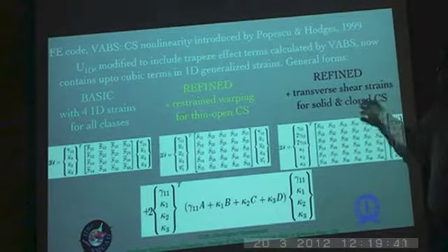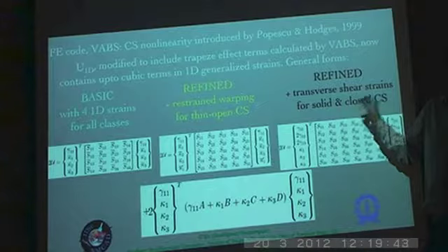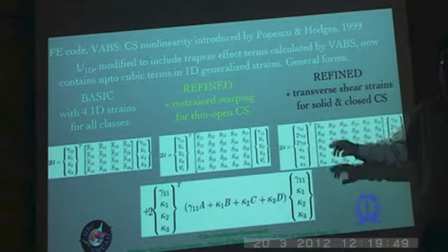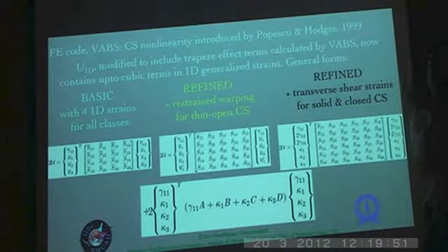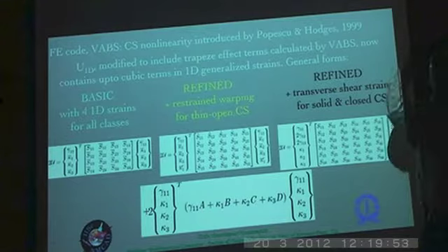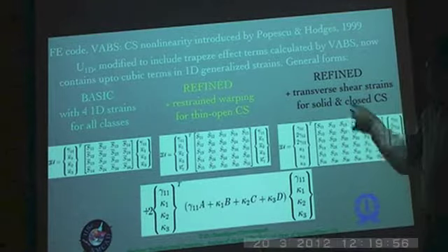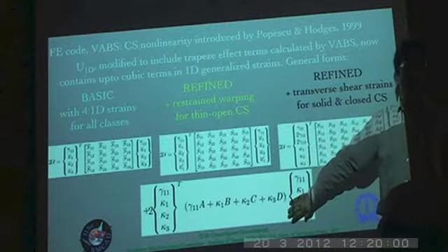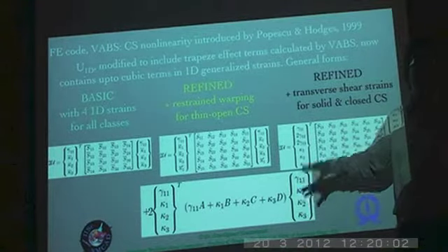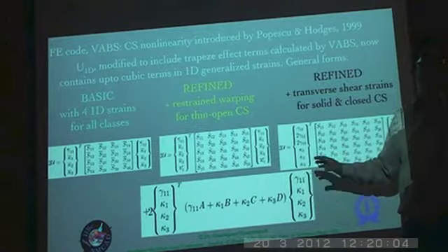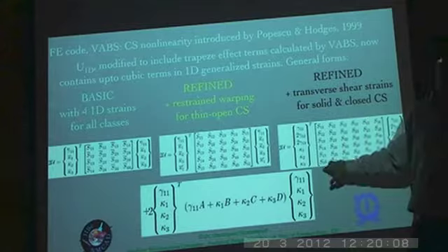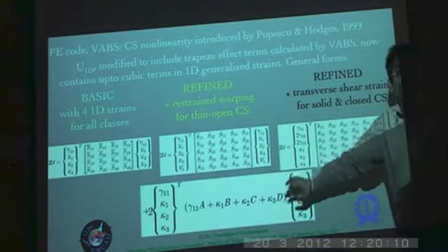So that is an exceptional case in this particular category, where you have a closed cross section but with thin walls. But if you have a closed cross section with thick walls, or solid cross sections where there is no distinguishing factor between various dimensions in any direction, then basically you will have only this in the first order. You have to go for a second order approximation to get this, but it is engineeringly irrelevant because they are much smaller compared to the effects of even the transverse shear. So typically you don't even need that.